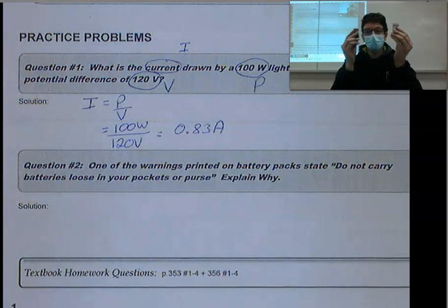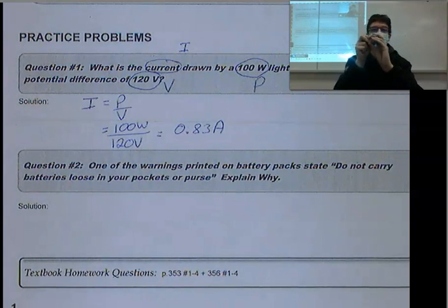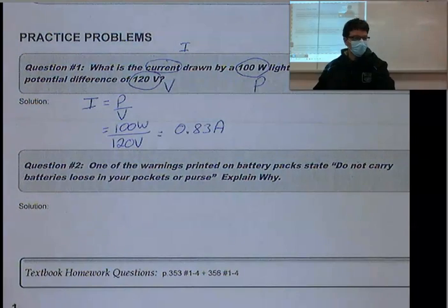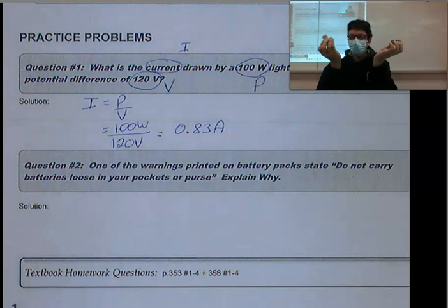Okay? If you are going to carry them, then you should, especially over 9-volt batteries, put some electrical tape covering the top. Or maybe keep them in a separate plastic container on its own. Not together in the same container, but in its own separate container. Alright, so getting back to this question, these can connect and form a short circuit, which is again what you don't want to do. So what you can do, even when you dispose of them, is put your insulating electrical tape over top of them before you put them into a disposal bag, which then you should bring to a proper recycling plant.